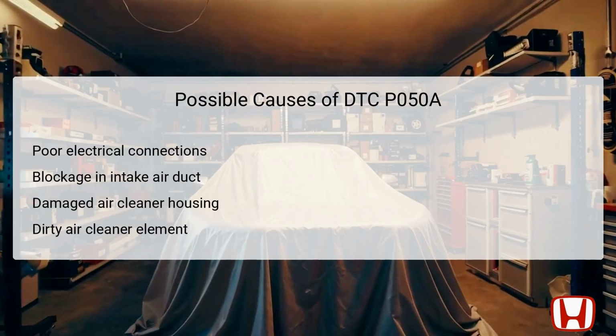Several underlying issues could trigger DTC P050A. First, poor electrical connections at critical components like the throttle body or sensors can lead to incorrect readings and subsequently contribute to idle performance issues.